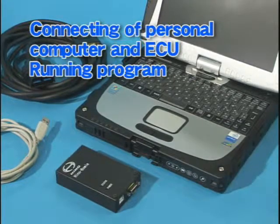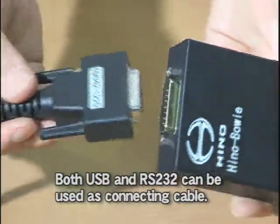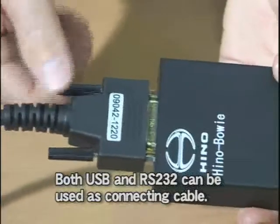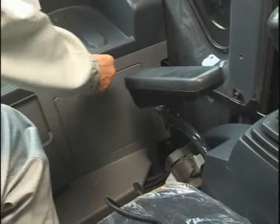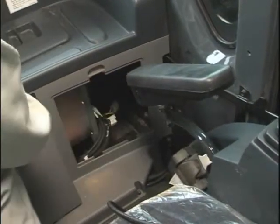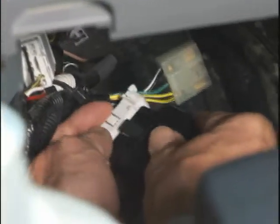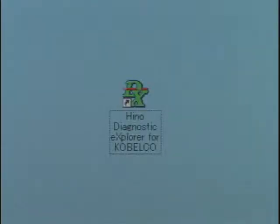Now, let's actually connect the personal computer with the ECU. Turn on the computer and start it. Connect the interface to the USB port of the computer with the connecting cable, and connect the interface to the other side of the connecting cable. Open the cover at the rear of the operator's seat and connect the checker harness to the connector of the ECU. Then turn on the key switch.